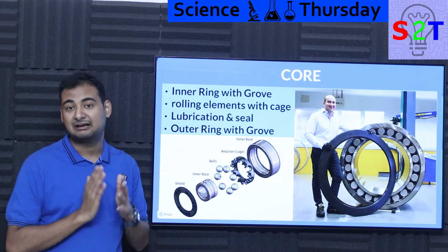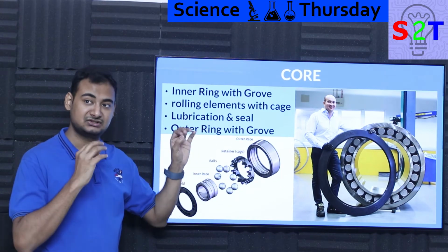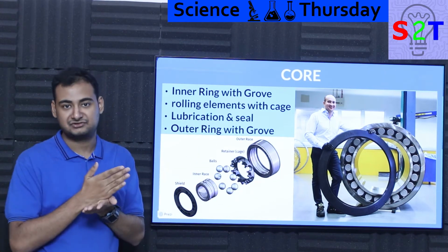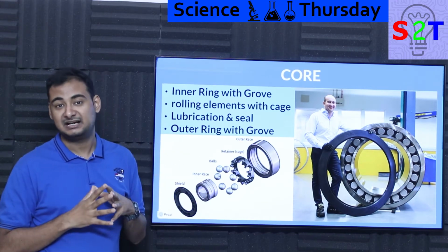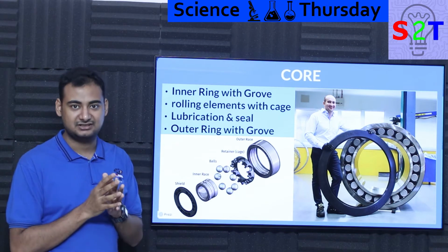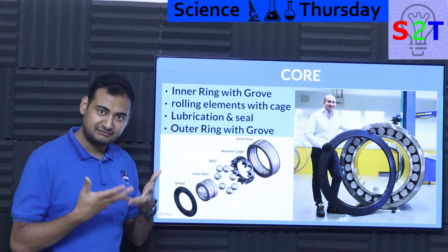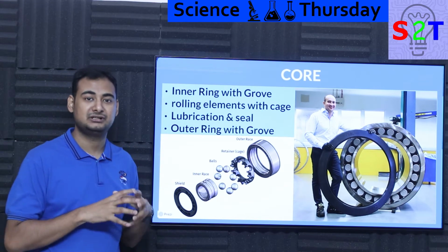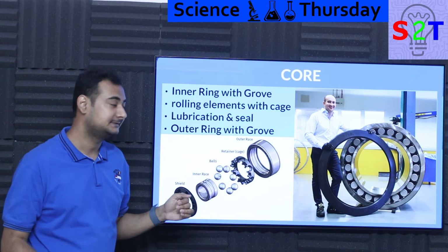And you have to utilize lubrication even in this sort of scenario. Of course, it consumes less if you just had shaft on shaft, but you still need lubrication. And lubrication has this bad tendency: once dust gets into it, it becomes sludgy, and more dust gets into it, and when it goes even more sludgy, it can gunk up to a point where your 10,000 horsepower engine could seize up simply because of a bad bearing.